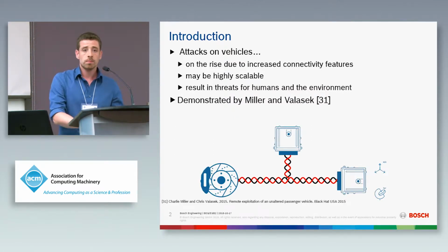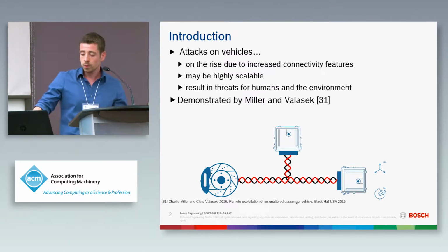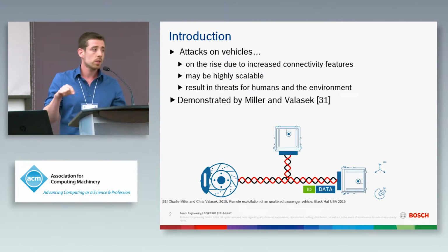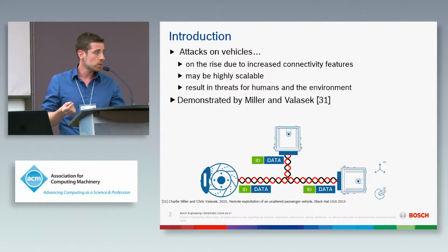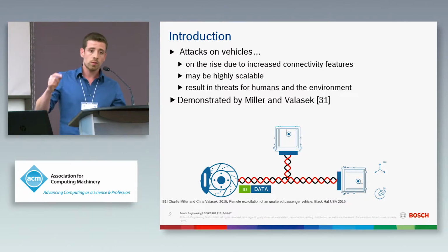Here we see a demonstrable topology with 3 ECUs, and one of those ECUs has access to some sensors, for example, an acceleration sensor. The ECU sends the values of this acceleration sensor periodically, for example, every 10 milliseconds, and for this it uses one ID, for example, 10. Potentially every ECU on the bus can receive this message, but only if it's configured to, it really will do. And here, for example, only the brakes use acceleration data.